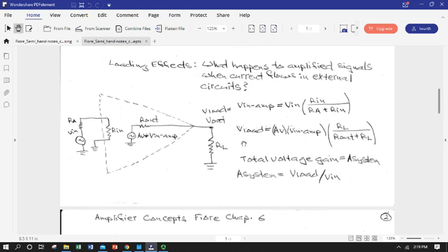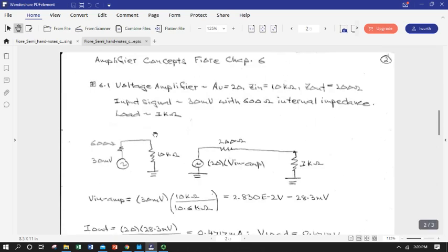And then when we get to chapter 7 and we apply this to some actual real simple bipolar junction transistor amplifier circuits, we'll see this happening for real with some voltage generator inputs and then some loaded outputs. So keep this in mind. We'll see this again in some circuits you can actually build and measure. Okay, so let's define a new gain, the system gain, which is the voltage drop over our load, which we're going to say is V out, but this is V out if we actually are going to flow current, divided by V in, which again is not what actually gets into the amplifier. It's V in here. So let's see how this works.